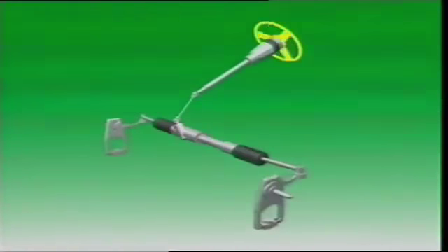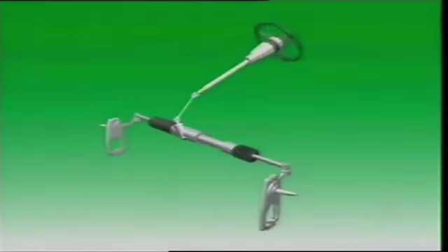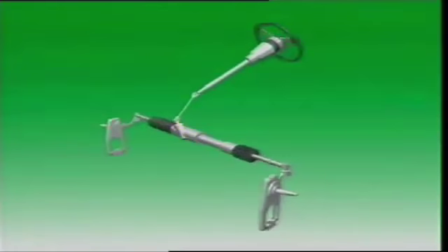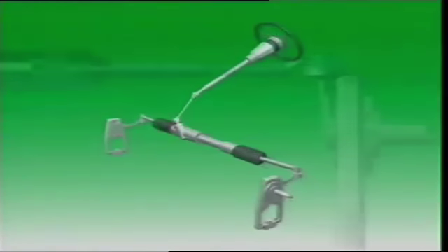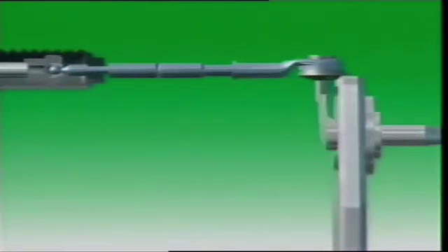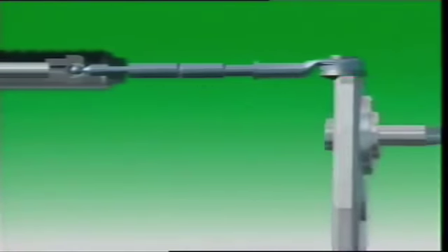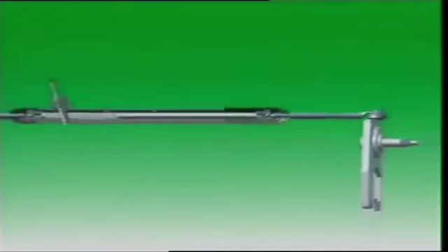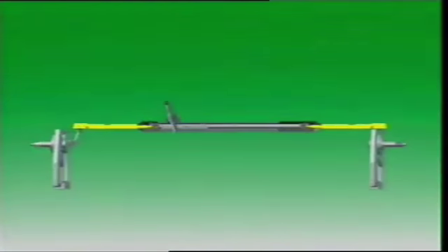Movement of the steering wheel is transferred through the steering column, intermediate shaft and universal joints to rotate the pinion, which moves the rack from side to side. A tie rod with a ball swivel at each end of the rack relays the movement directly to the steering lever on each wheel assembly. The rack can thus be considered as the center track rod of a three-piece track rod system.